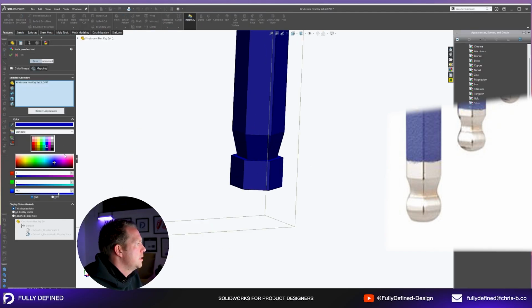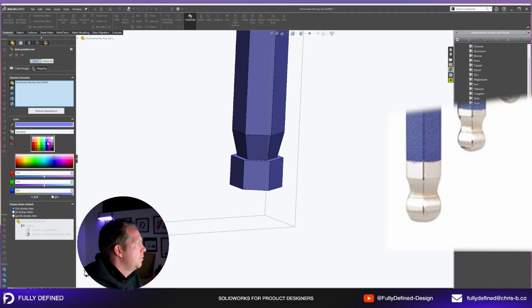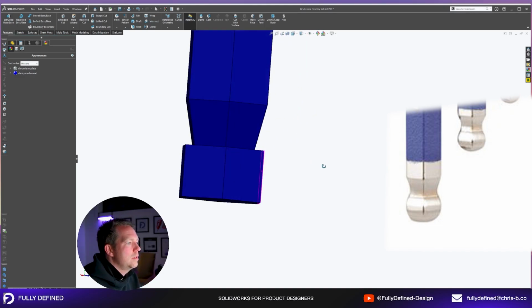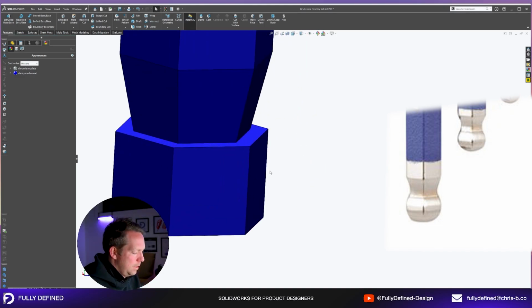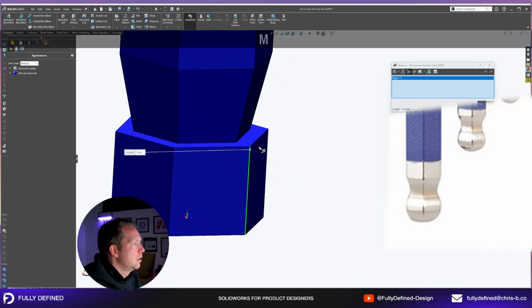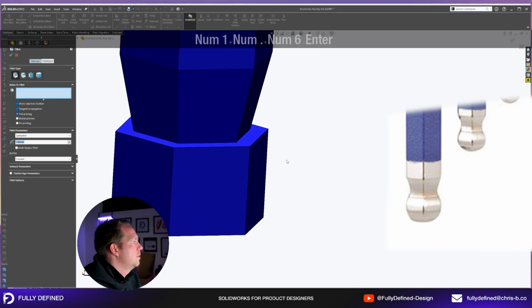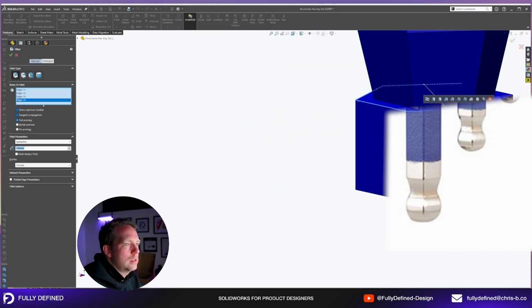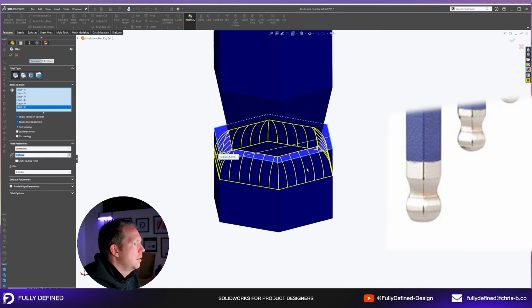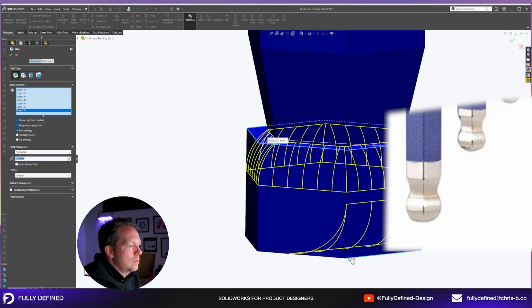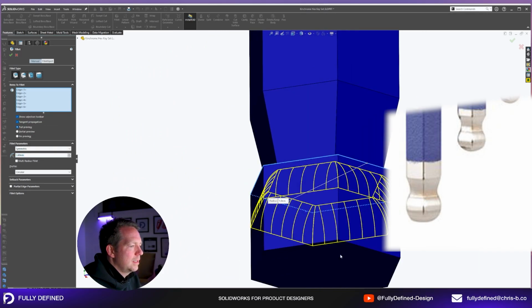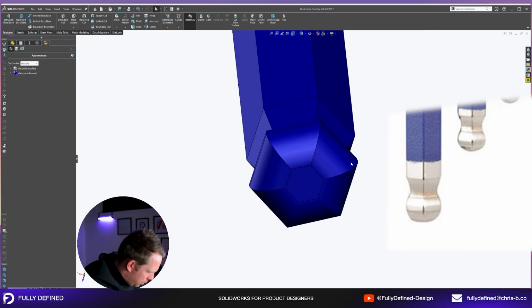This color is a bit dark. Let's bump that up a little bit. All right, next, now we have to do these little curves on the bottom, and it really just looks like a fillet that's going around. So the length here is 3.2. So if I do a 1.6 fillet, what does that look like? And I want to do that on each edge. Is it going to work or not work? That looks to work. And what's it going to do if I select all the bottom edges as well? Which I could do by selecting the face. That looks pretty good. I think so.